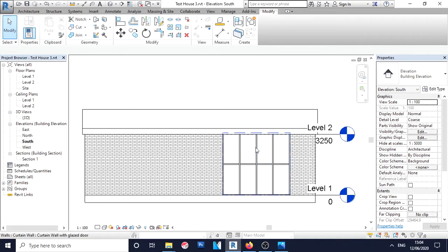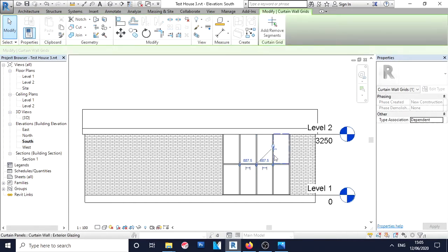And as you tab, you should also see a dashed line. That dashed line is the grid line on which the mullion is positioned. So as you tab, you should see all of these different elements being selected. And once you are able to select the grid line, it should give you the accurate dimensions between it and the nearest object.